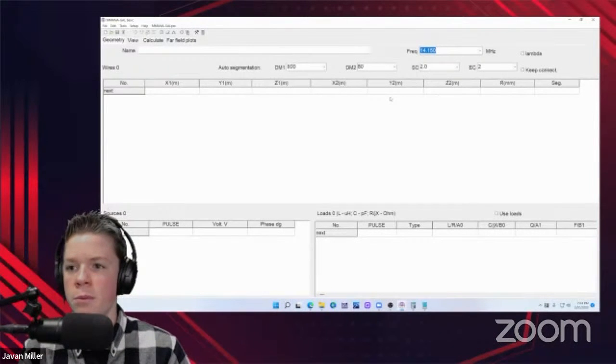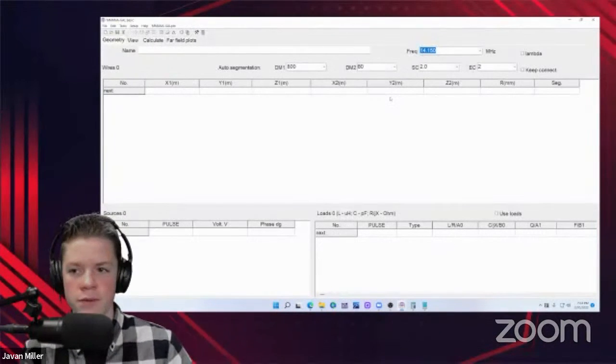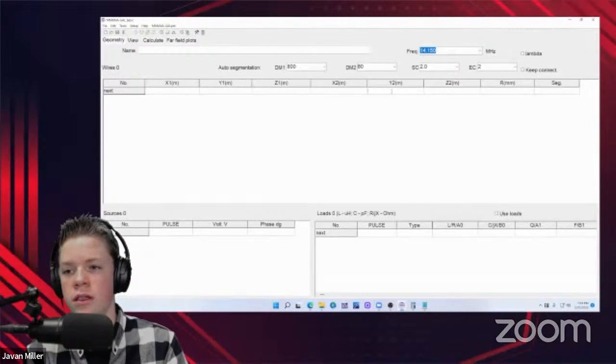So Rick, are you thinking 80 meters for the end-fed half wave? Yeah, I think that's what we could possibly get away with up at the UPD radio. We do end-fed with a chameleon balun. I think the chameleons are lower, something in the range of 6-to-1 or 9-to-1. I'm not sure.